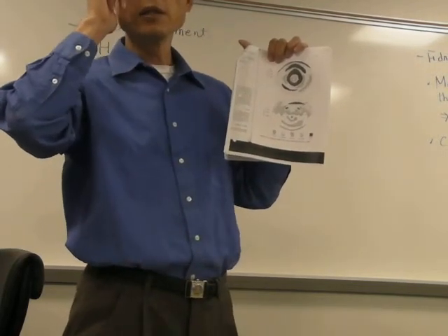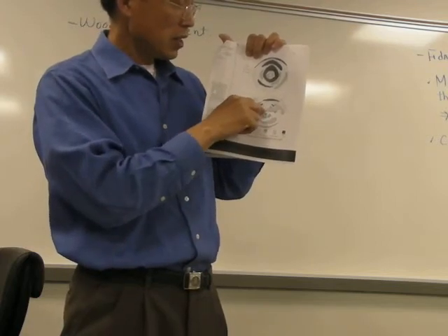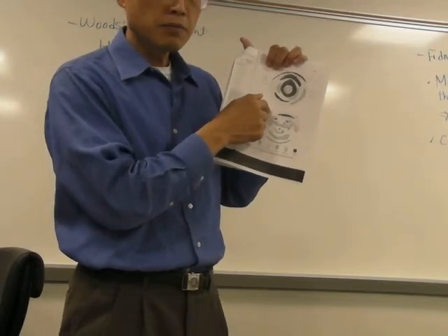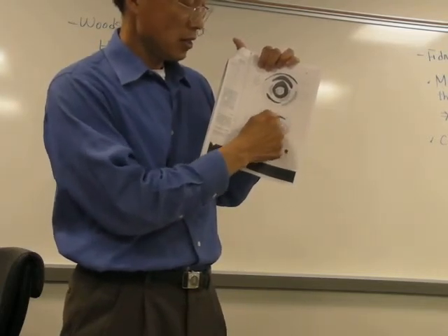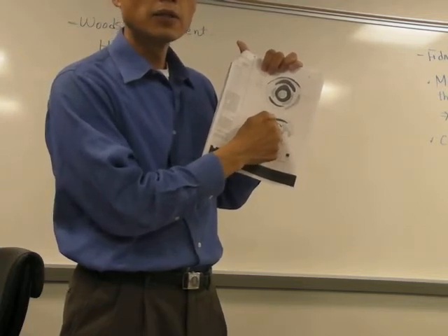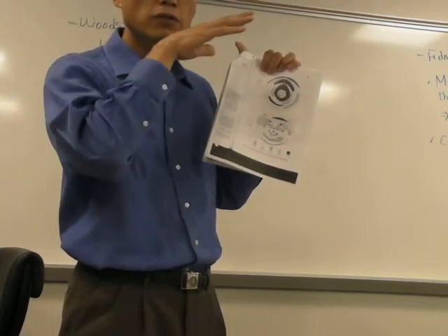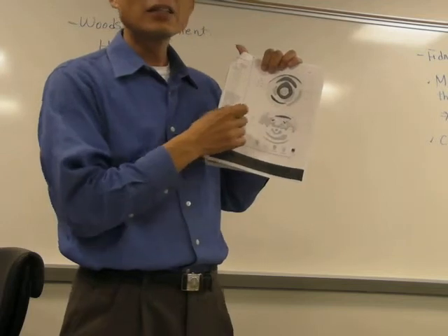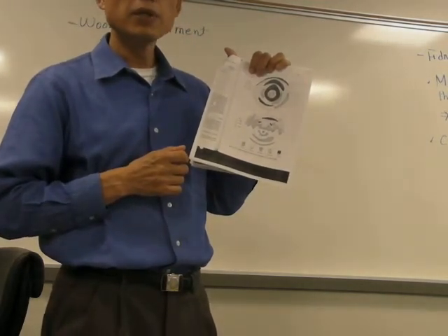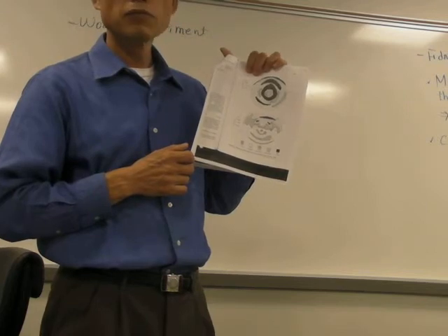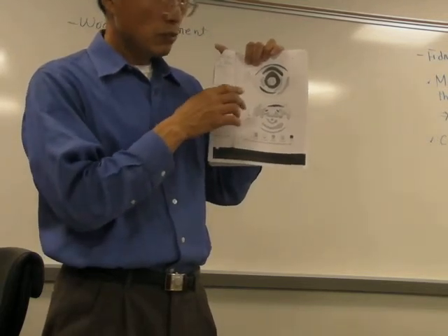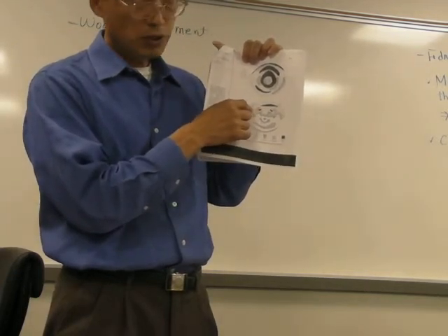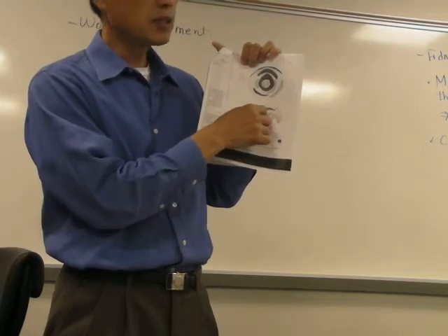So one of his findings is, okay, when we install our trenches at 180 degrees, only this area is the area that has satisfactory low amplitude. Those areas, amplitude was cut down a little bit, but it may not be enough. So when we design semicircular trenches like this, probably we should assume that those areas are not really effectively controlled.